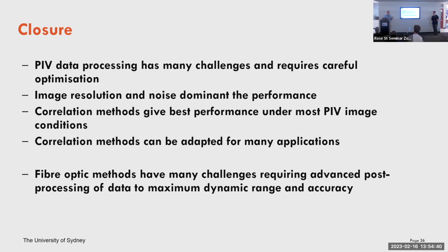But now with the sensors coming on board, which offer these really high resolutions, potentially we can go back and revisit that, and we could do full digital holographic PIV. And then the issue of ambiguity and ghosting and trying to track things goes, because you can then just digitally fly through the reconstructed volume and find everything. So that's where it might go.